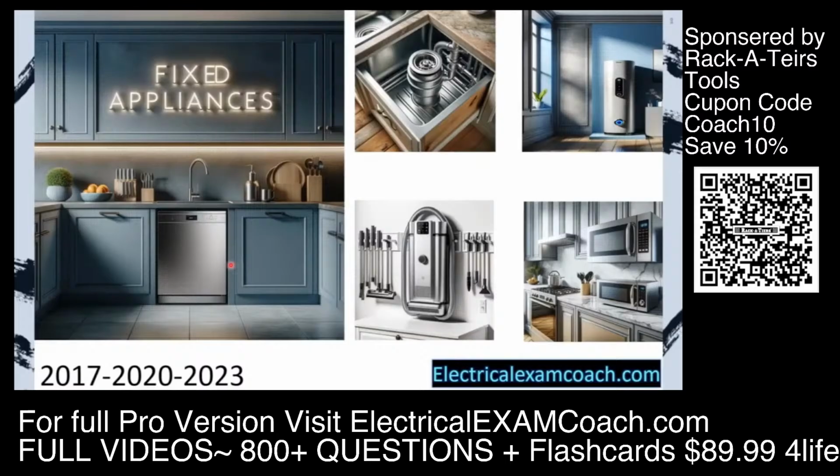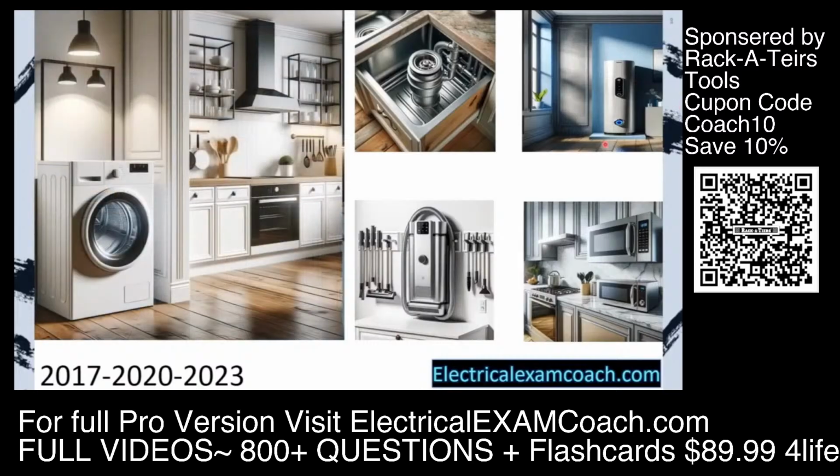And there's a special way that they calculate them when doing a whole home load calculation. What it does not include is dryers or ranges. We're actually going to deal with those separately. So this includes all other fixed appliances except for dryers and ranges.